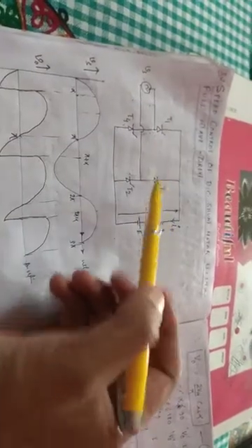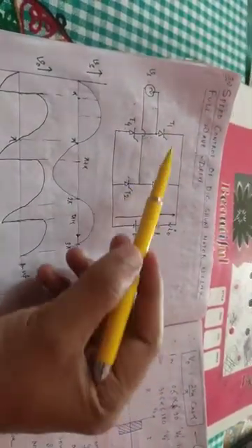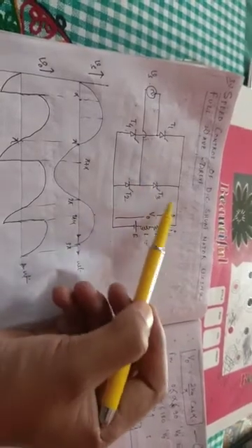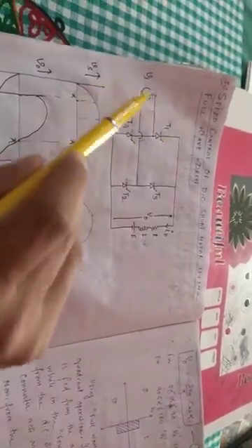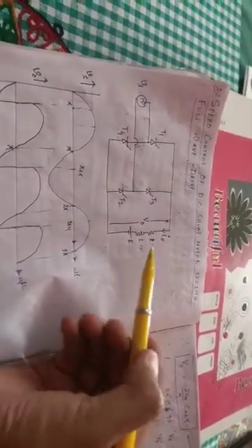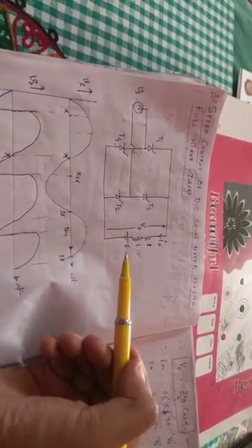In this lecture I'm going to teach you, in the control of electrical machines section, the solid state control of DC drives using a full wave control converter. As you can see in this diagram, it is the full wave control rectifier, the control converter comprising the four thyristors T1, T2, T3 and T4. It's fed from an AC supply, and this is the RLE load depicting a DC motor. That is, a DC motor can be represented by an RLE load.